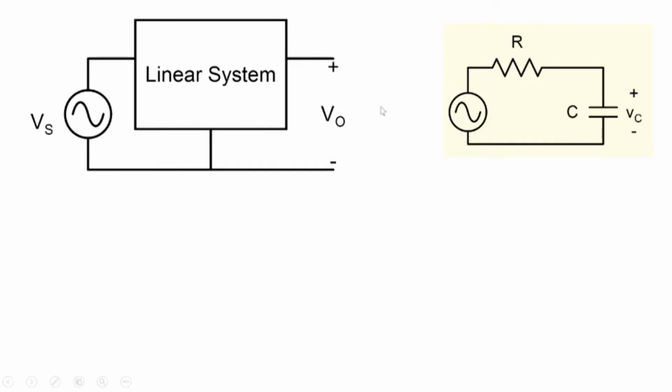What we do is we excite it with the sinusoid and we look at its response as a function of the frequency of the sinusoid. Note that in a linear circuit, the amplitude doesn't really matter. So we apply 1 volt and we'll get some output. If I make it 2 volts, the output will also double. If I make it 3, the output will also triple.